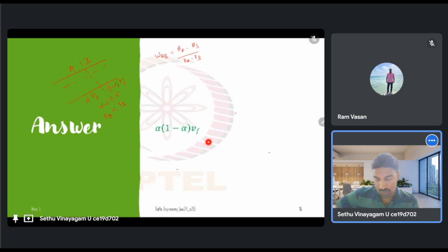So in other words, the shock wave that is generated is a backward moving shock wave, right? Which means a low density traffic state is meeting a high density traffic state, right? So it is going to generate a shock wave in the negative direction. Which means this traffic state is going to propagate in the upstream direction. Okay, so we are given the relationship as well.